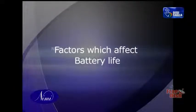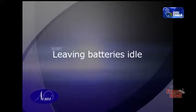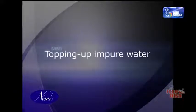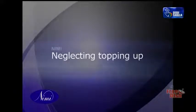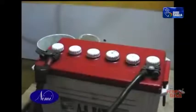Factors which affect battery life: undercharging, leaving batteries idle, topping up with impure water, neglecting topping up, container damage. Specific gravity test. Keep the battery on an elevated wooden workbench. Remove all the vent plugs.